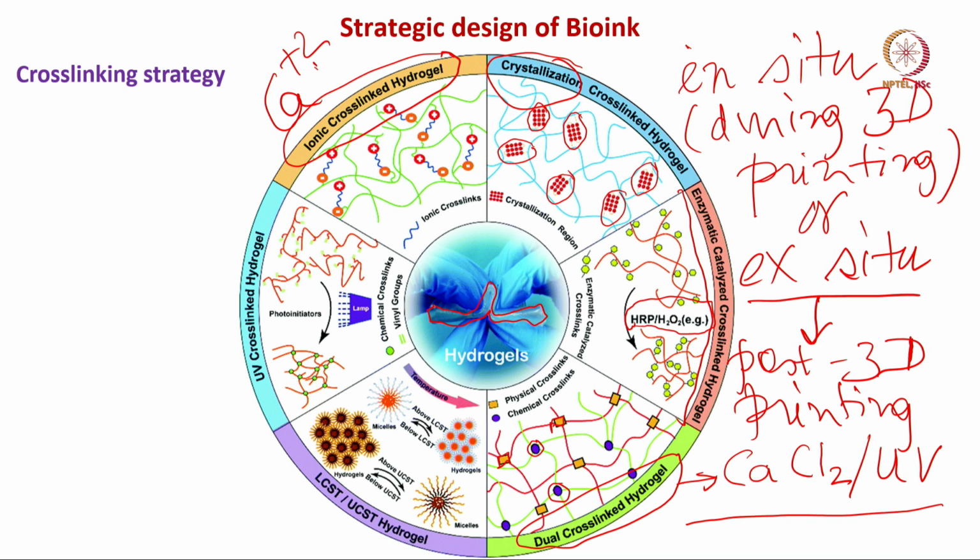And more traditionally you can have UV cross-linked hydrogel. So essentially in the hydrogel structures you need to add photoinitiators, typically Irgacure for example, and when you add these photoinitiators and then expose this hydrogel structure to a UV lamp, this cross-linking essentially boosts the properties, or increases the strength, and also makes the structure more compact, and as a result you can expect the porosity also decreases.